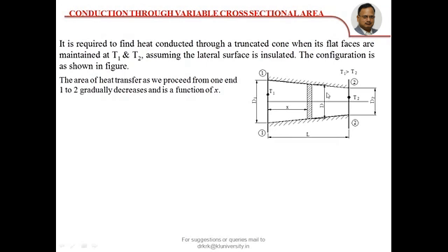Let the diameter of this elemental strip be d. Because the thickness I am assuming here, dx, is very, very small, I assume d is the same on both sides of this element having thickness dx. So that is why you have to choose a very, very small element of thickness dx, negligibly small. So d won't vary then. Now the cross-sectional area of this elemental strip is pi by 4 d square at this left-hand face, and also on the right-hand face approximately pi by 4 d square.